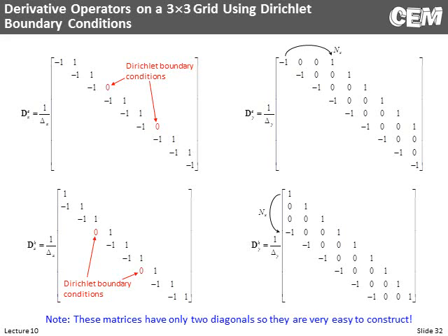And just like before, when we did the x derivative operators, we had these intermittent boundary condition corrections. So now that we're in two dimensions, we don't really have a continuous row of positive ones. We have some corrections due to the boundary conditions that we put in there. And the derivatives for both E's and H's have those. But since it's only two dimensions and our last dimension is y, we don't have any corrections here. We have two pure diagonals.